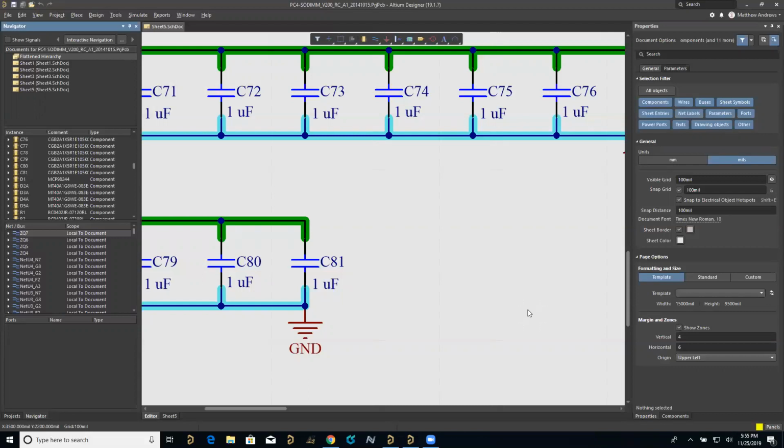But one of the things that you do have to do, while you add components to the project in the schematic environment, to actually build that data model, is compile the design to make sure that the new component that you add is in the project structure. And so with a really large project, depending on the size of the project and the number of components that you add to it from the last compile operation, it could potentially take a lot of time to run that compile operation to build the new data model.